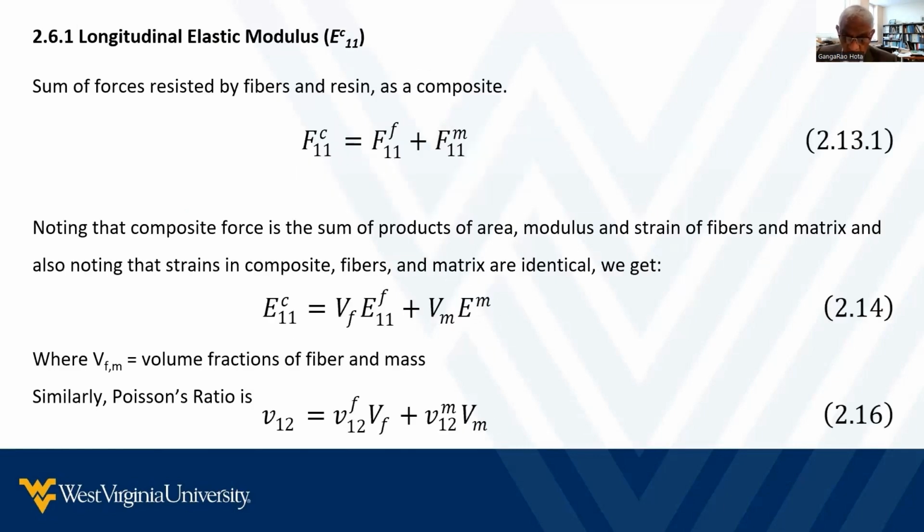In the next slide, now I'm establishing an appropriate equation for Young's modulus, E value, of a composite by a simple force equilibrium equation, where the longitudinal force resisted by a composite of that infinitesimal element is equal to the sum of the forces resisted by the fiber and the matrix, which are given in equation 2.13.1.